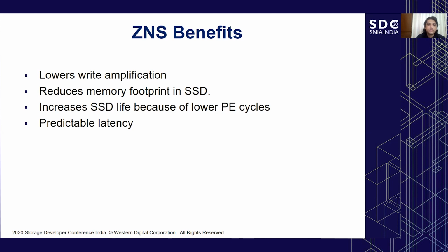And so it reduces the write amplification, and by reducing write amplification, we are increasing the throughput, because the device is not busy doing its own garbage collection, and all of the device bandwidth is available to the host. And also, by reducing the garbage collection at device level, we are reducing the program erase cycles at the device level, hence extending the life of the SSD.